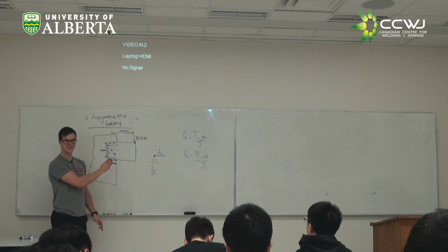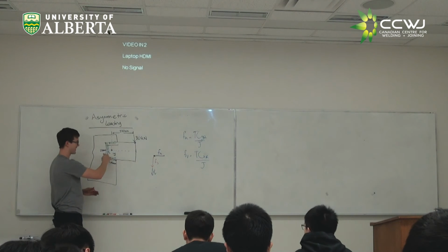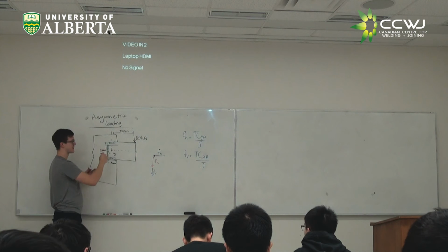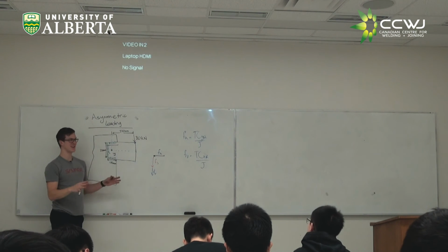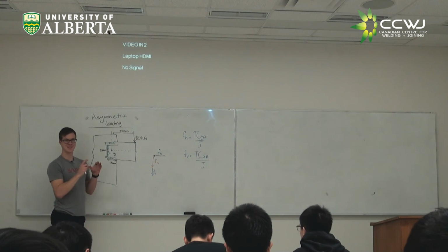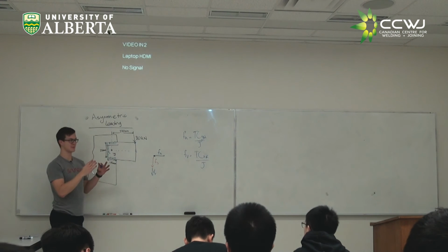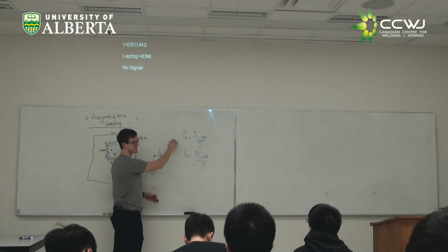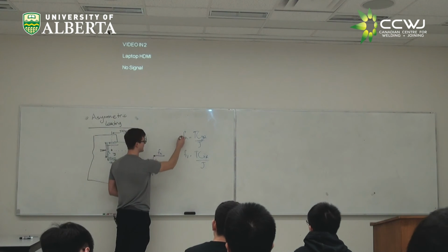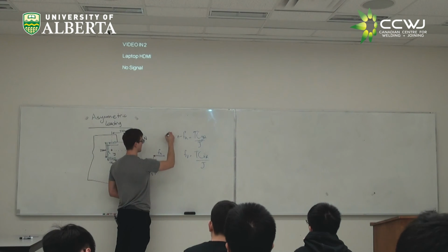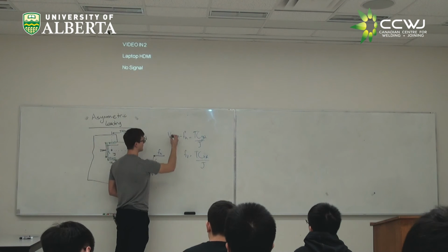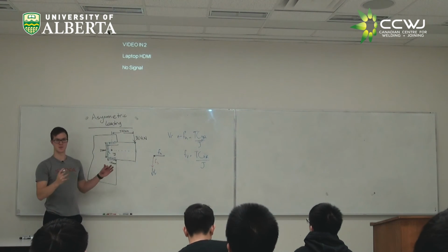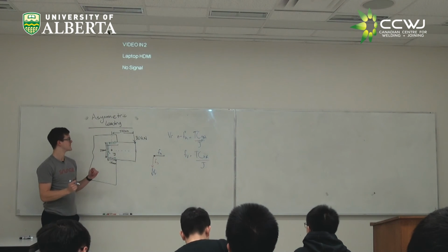What we're basically looking at here is if we have a moment of inertia which describes our weld, then we have a moment that we're distributing over that area and a length, we can end up with our required resistance per unit length. So this FH is equivalent to our VR, right? FH is our resistance per unit length of weld.